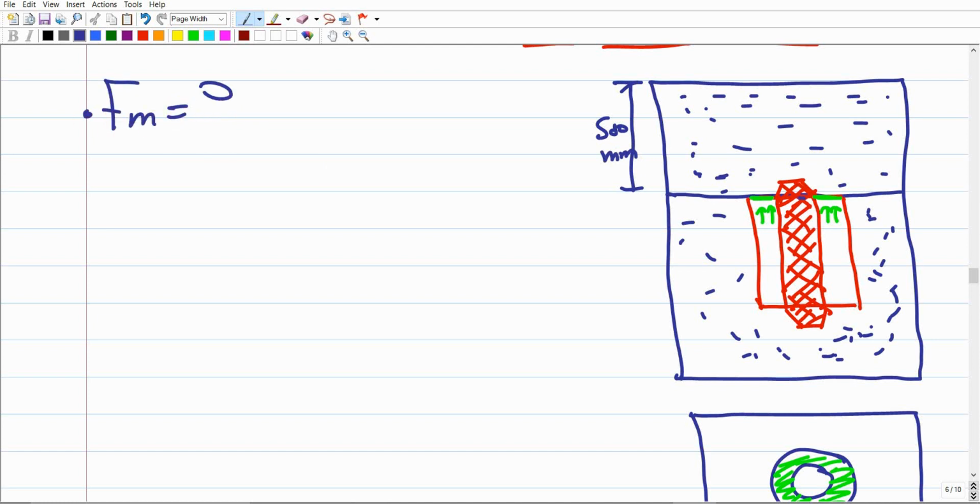So what does it mean if I ask you to calculate the buoyancy force? Simply, the buoyancy force is going to be rho of the metal times g times h times A, minus the portion of the metal that is located in the cube. But none of the casting will be located in the cube. All the casting is completely located in the drag, so there is no negative W_C here. W_C will definitely be zero.